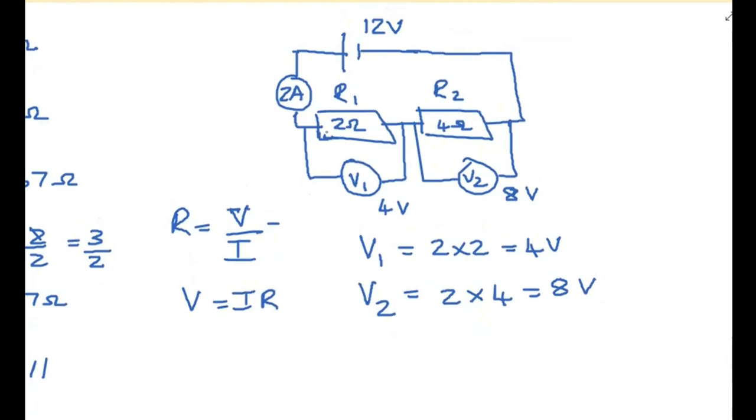Now you need to start seeing potential difference as energy, essentially. There's 12 volts, and it's joules per coulomb, but I'm not going to say joules per coulomb every time. There's 12 volts available. That has got to be shared around the circuit. So when these charge carriers move through the circuit, they are transferring energy. Now, if we look at wires and we make the assumption that our wires have negligible resistance, that means they are not transferring any energy in the wires.